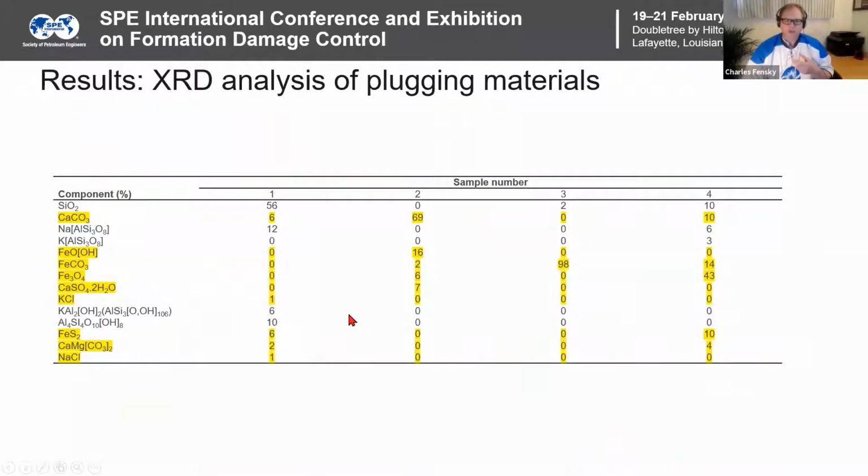When we looked at these samples, we quantified what was the plugging material that was closing up those doors, which are preventing things from flowing through. It shouldn't come as a surprise that there's lots of sand and fines. That's the purpose of the device. But what was also key about what was blocking it up was the accumulation of scales that was holding those blockages together. So in this sample right here, we have examples of calcium carbonate. We have different corrosion-based scales. All of those items are binding up that material in different concentrations.